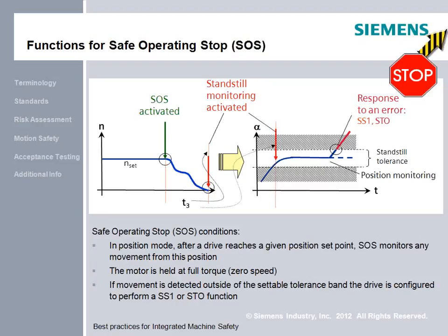My fail-to-safe implementation in my application software is most likely going to apply the mechanical braking system as the redundant or backup brake system, and in this case, being able to avert a physical axis from dropping by using the brake as the reserve. So safe operating stop is just that. It's a methodology for controlling a machine at a standstill condition.